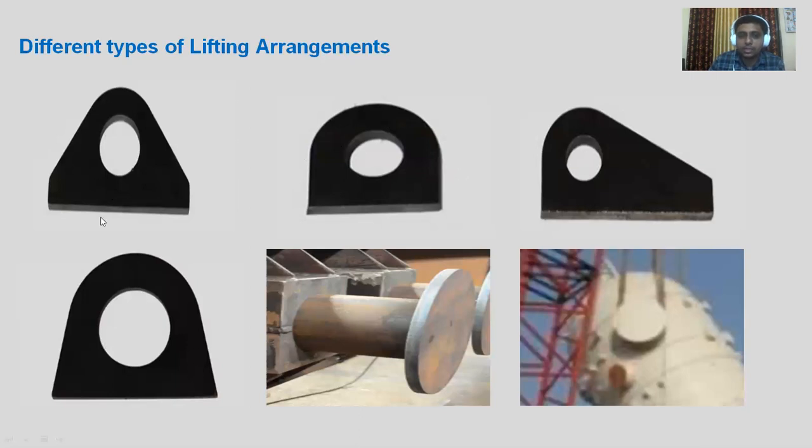So this is also nothing but this, but it has a more curved radius. It does not have any straight portion like this, and this is a typical type of trunnion. So a trunnion consists of one pipe and one closure plate. Here it is welded on some square box, otherwise it will be directly welded on your vessel. So this trunnion will be directly welded on the vessel.